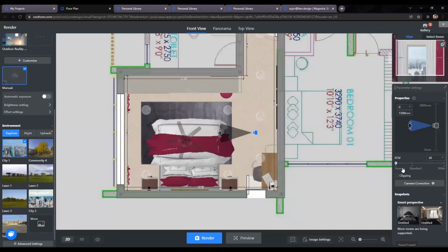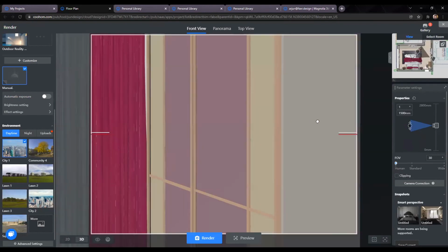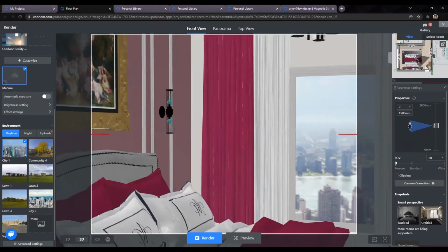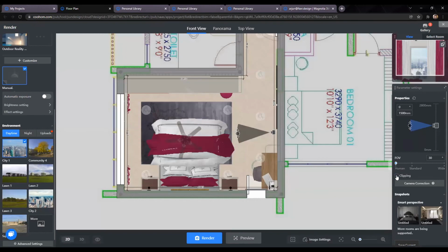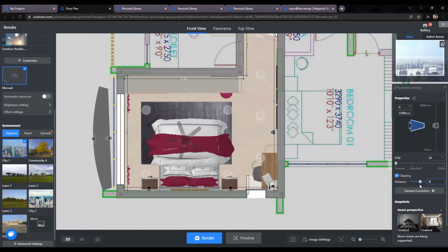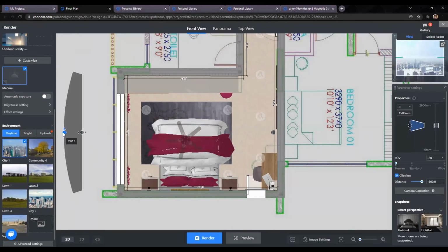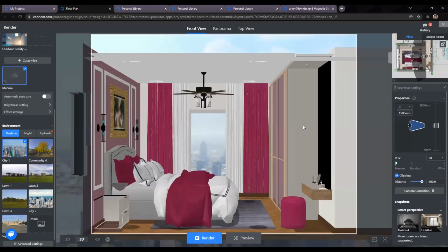After setting the camera to human, the camera can only be moved till this point, till this wall. So the focus will be only on this part of the room. So I'll have to expand it. I can do that by going to the clipping option. You just click on the clipping tool, and you can adjust the clipping length. I'm gonna add a clipping length of 600 mm, which will give me a more elaborated, elongated view of the room.